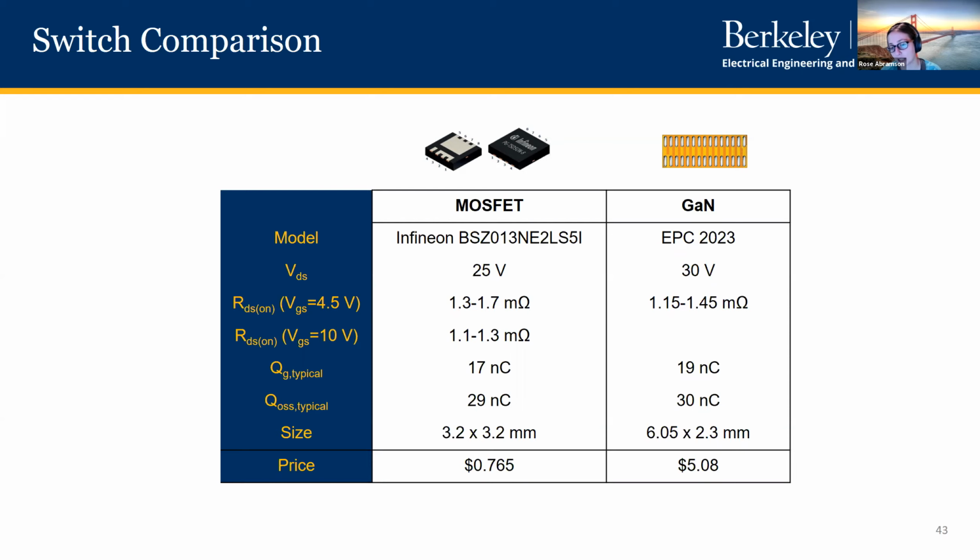Another common question is exactly how are you measuring the converter volume? So some people do this by summing up all of the major power conversion elements like switches, inductors, and capacitors. Some people do what we do, a box volume of just the conversion stage.